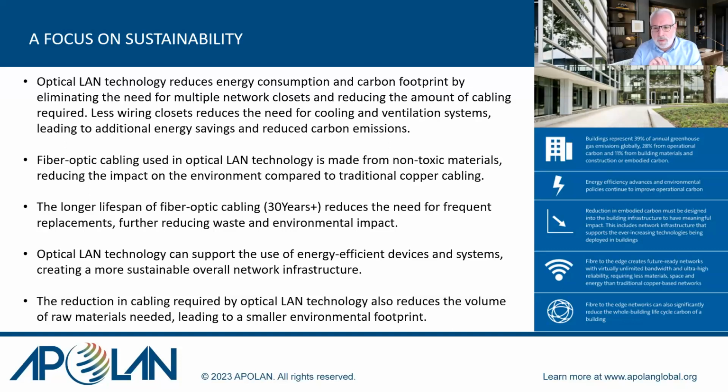But ultimately, the key things that we can do is, because of the benefits of this type of technology, we can reduce things like IDF closets. And by reducing IDF closets, we can reduce the amount of CRAC units or cooling that's required and the amount of power that's required. So that has an immediate impact on sustainability and carbon emissions. Fiber cable is a much less toxic material than copper cables. And to actually manufacture it, it produces far less carbon than traditional copper cable solutions.